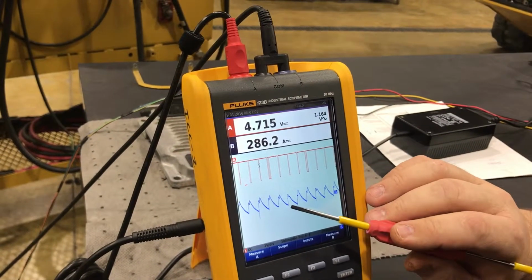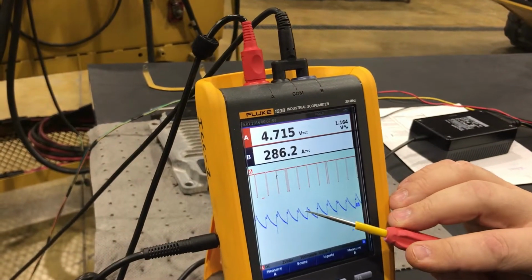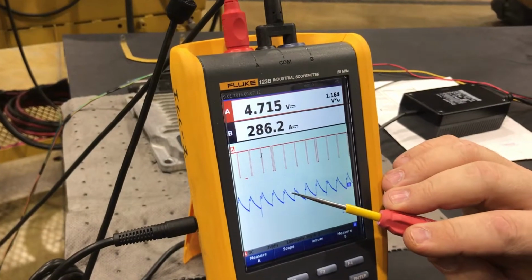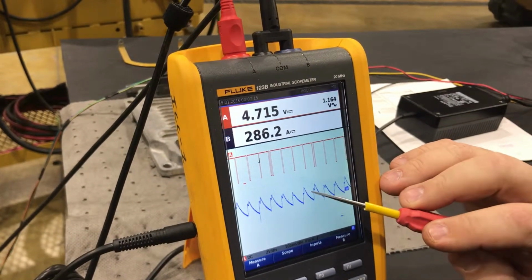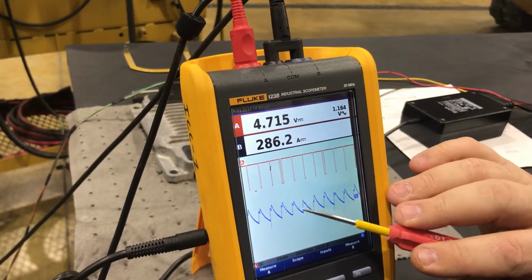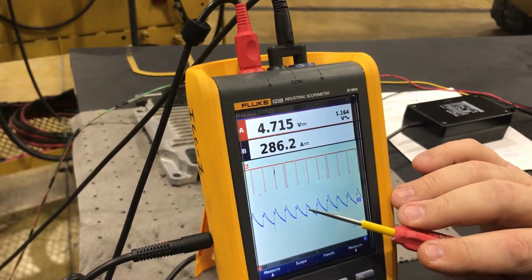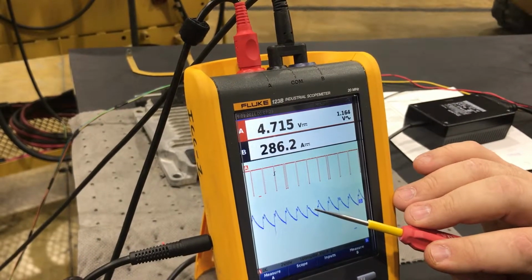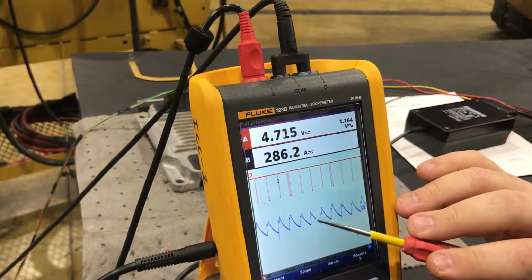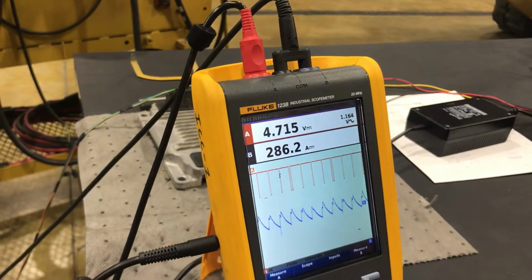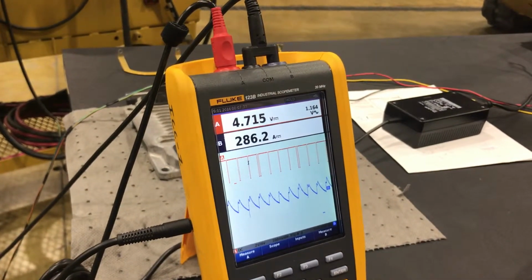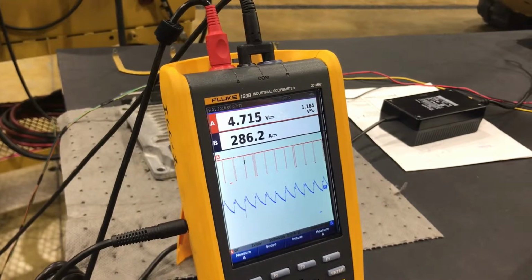Okay, so if I look at it here, I see number 1 is back in line. Remember, I'm after this one, so I see number 1 is back in line. Ooh, I see a little dip here. I see this one come up and this one come up. So I'm going to guess that he loosened one, and there's not much difference here, right? All he's doing is loosening a glow plug a few turns. I can see here that if I follow my firing order, this is 1, number 3 is my problem. Am I right, Lucas? Good deal. So I can see a weakness there. Obviously, the worse it is, the more it's going to come into play.